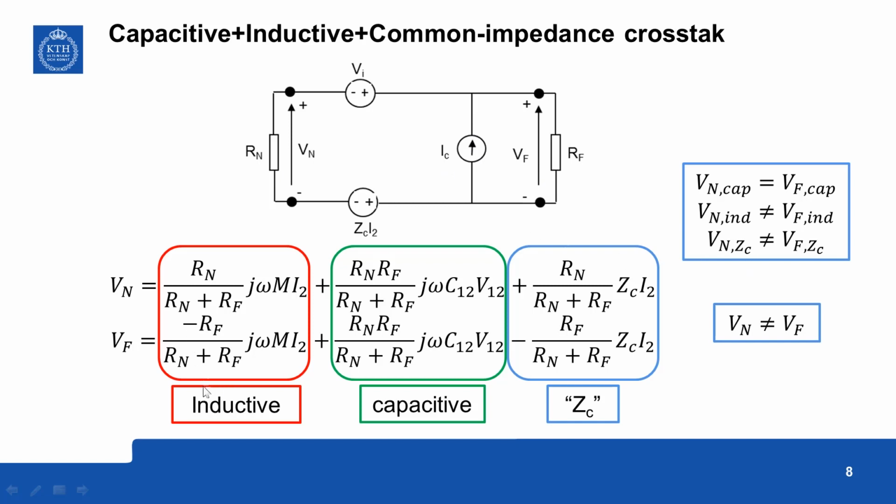So if you write the equation, here this is taken as positive polarity, so this is due to this term, sorry, this is Rf, so this is this term, because Vi is equal to minus j omega I2, so this minus is coming from that one, and this is this minus and minus j omega I2, so they cancel, so it becomes plus.